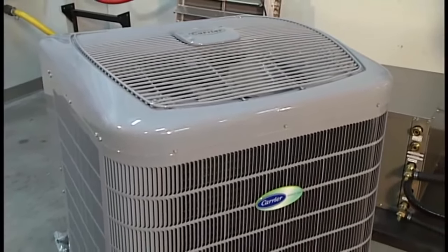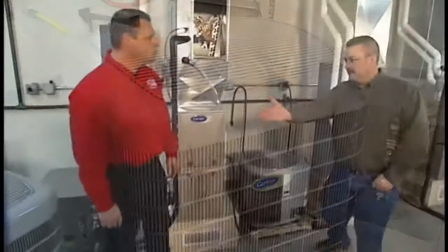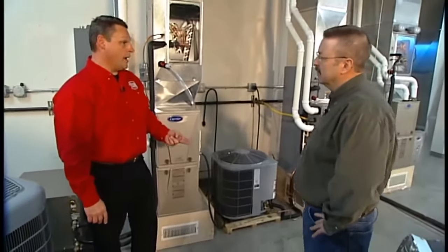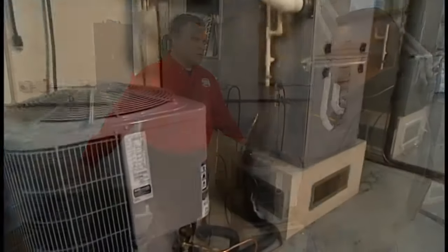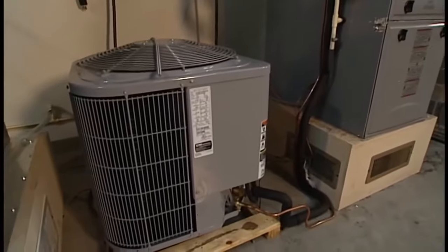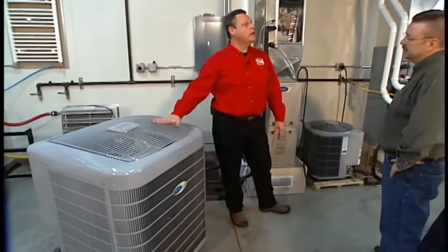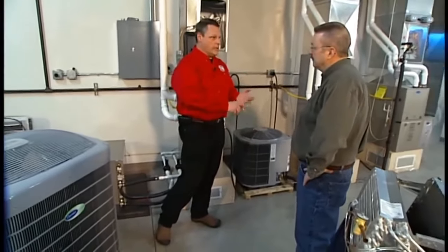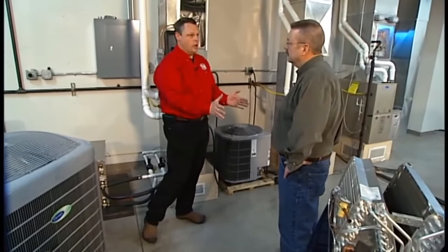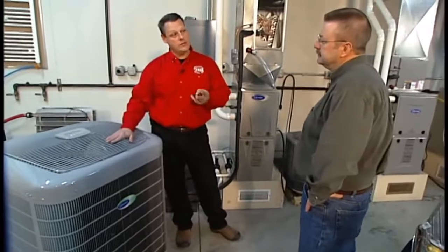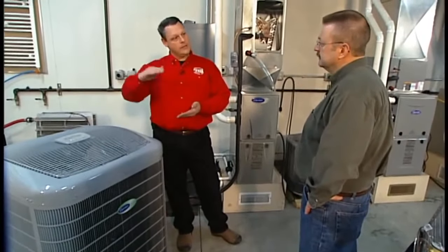Now over here there's a smaller sized condensing unit as compared to this one here. Is it just based on the size of a house? Two things go into that. These are actually relatively close in the same capacity, but there's a difference in their efficiencies. This is a 13 SEER, this happens to be a 16 SEER. Another thing we have to consider is what we are doing within those cabinetries. This is an entry-level model, so it's going to be on-off, 100% output when it runs. The advantage of this model as well is it brings us two-stage capacity through the compressor. Again, it's an upgraded model.